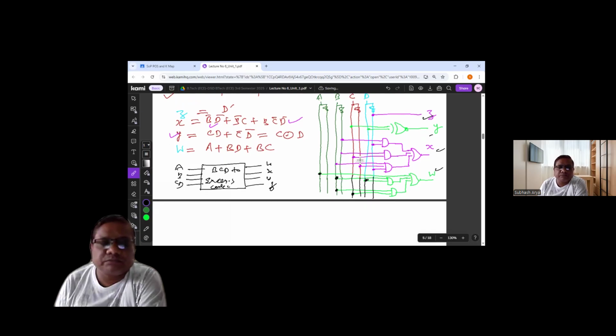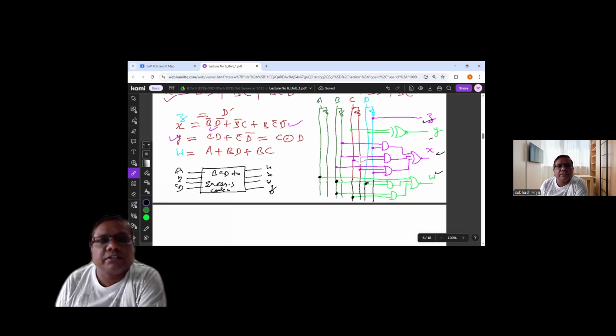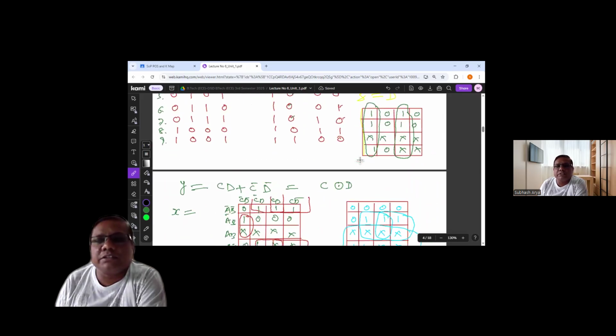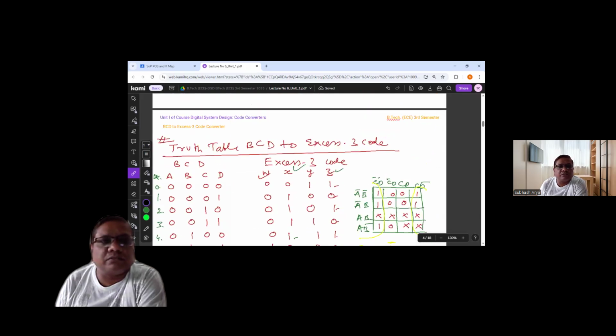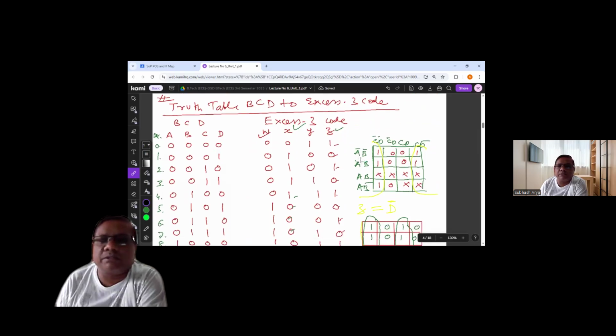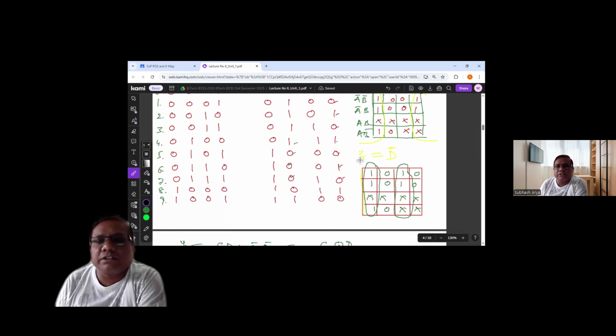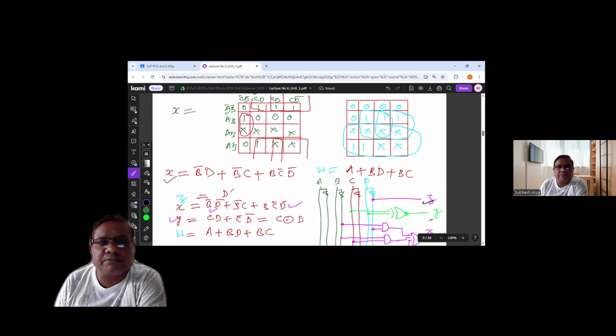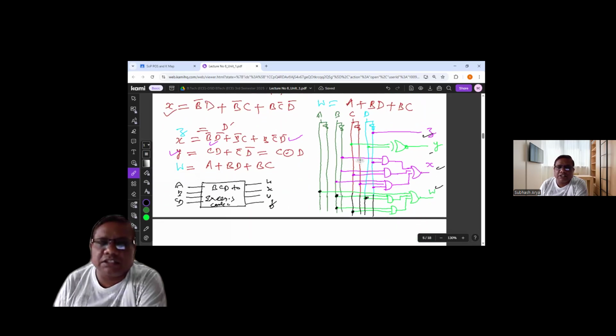With this, the class is concluded today. What we have learned is the BCD to Excess-3 code converter. We started from the truth table, saw the expressions of W, X, Y, Z, got the outputs in terms of the input variables, and then implemented them with the help of logic gates. With this, thank you for attending this class.